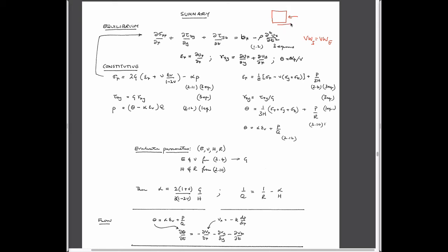if this is the x direction, then the stress that's applied in the x direction and how it changes from one side to the other, if it changes, then it basically has to be balanced by a shear stress in this direction, tau. And so if there's an imbalance of the normal stresses in this direction, it has to be balanced in some way by the shear stresses in the other directions, both on this top surface and also on this side surface, right?